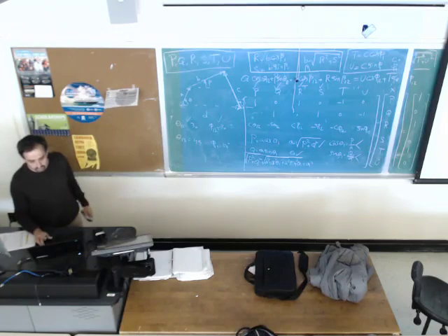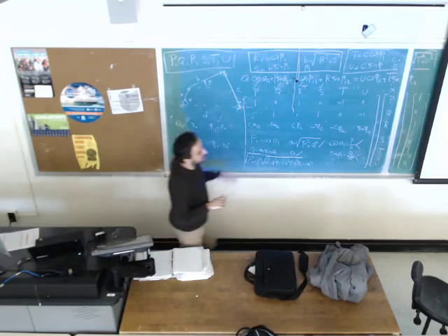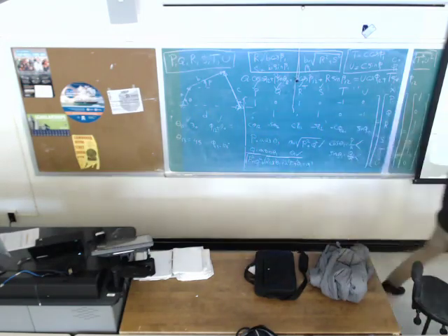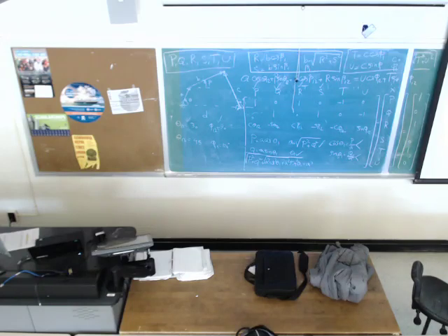I can ask you to draw the mechanism at the starting position, second position point, and the third position point. First, you pick O2 and O4 with the distance of 1 from O2. Then theta 1 is almost 61, pick 61. A is 1.02. You end up at this point with this angle. So this is one joint.